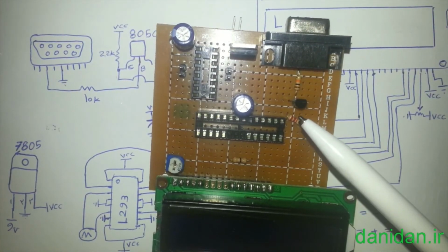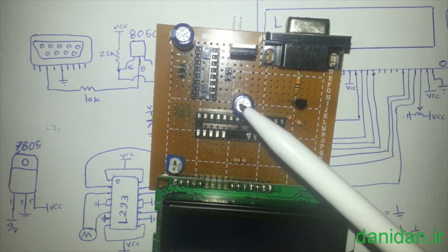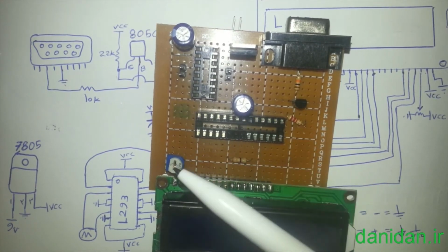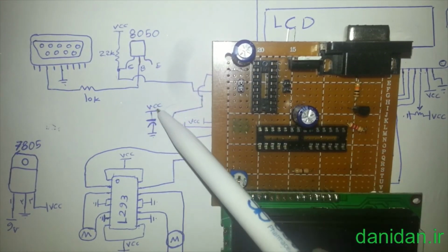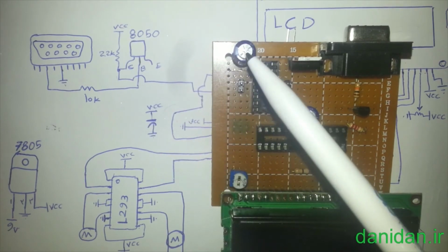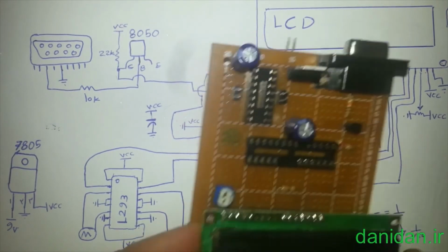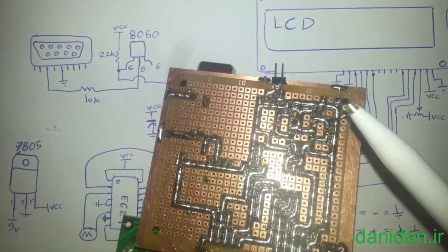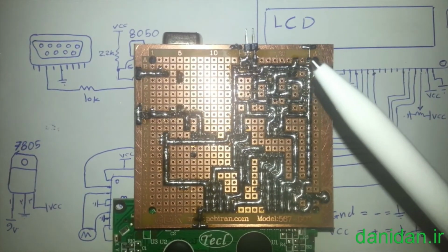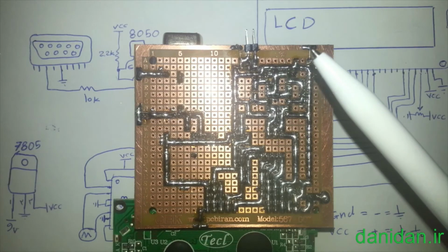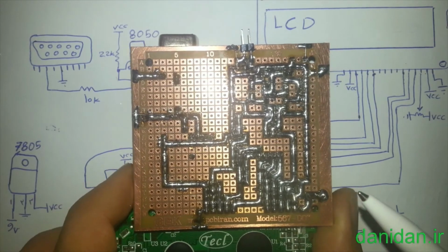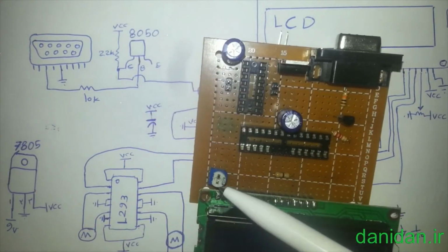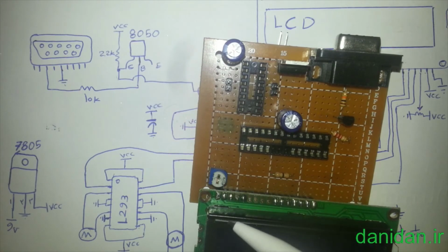And also to connect our serial circuit to our microcontroller, I use two resistors, one transistor, and I try to solder the capacitor right after the microcontroller. Also, I just use another capacitor just to be sure. It's not compulsory. Just to be sure, I just solder that on another part of my board.